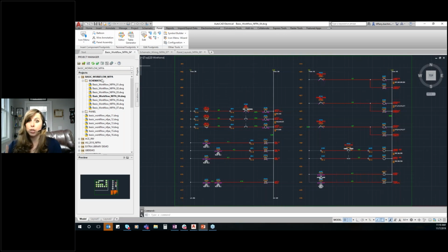So this is the first big difference between AutoCAD Electrical and AutoCAD: we actually work with our drawings via the project manager, and not by going up to something like File, New, or Open, because you don't want these files to all just be independent of one another. They are their own DWGs, so they can be opened by somebody who just has vanilla AutoCAD.